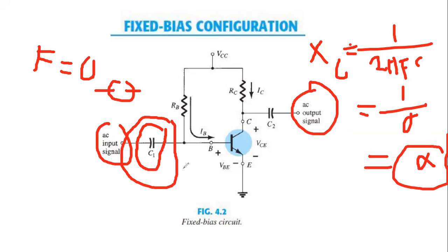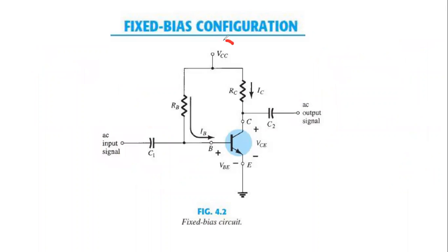We also discussed this type of notation. If you remember in the diode circuit, this type of notation is a small circle, and next to it is plus V, plus 5, which means this is the plus 5 volt. Here it is plus VCC voltage. You see that these two terminals, both the base and collector, are taken common here.